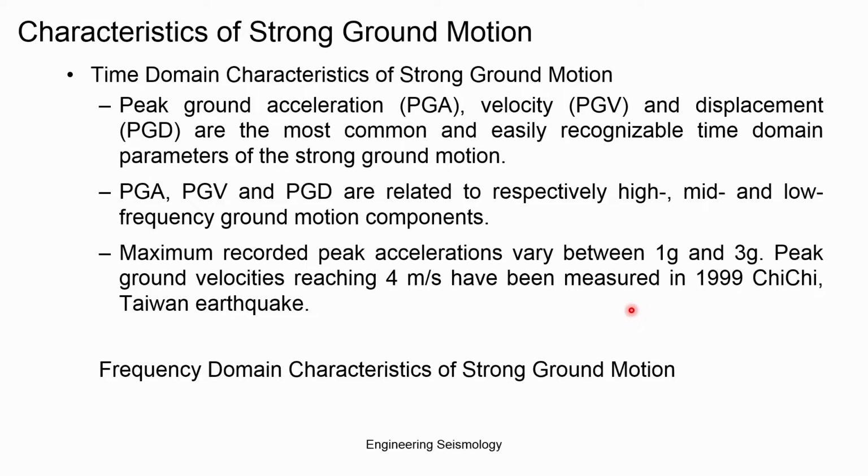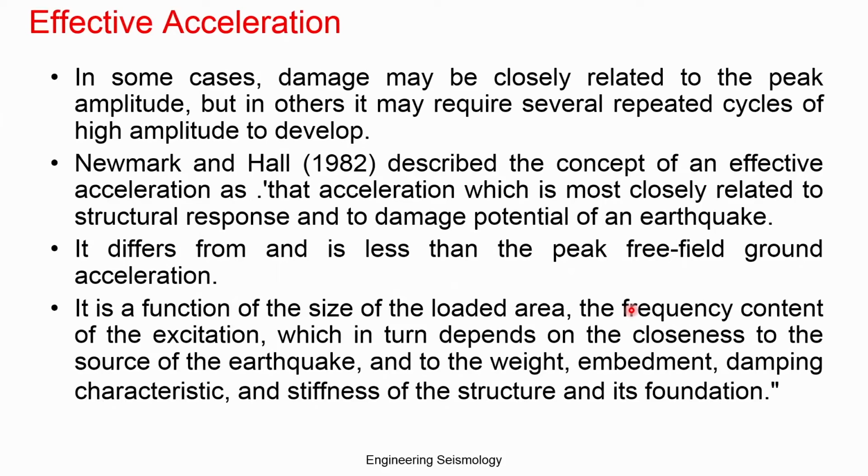So, if you have a structure which has some natural frequency, then we should see that this frequency does not match with the ground motion frequencies. Okay. So, that is the reason these peak values are estimated, which represent a different segment of the frequency. Okay. So, or controlled frequency kind of.